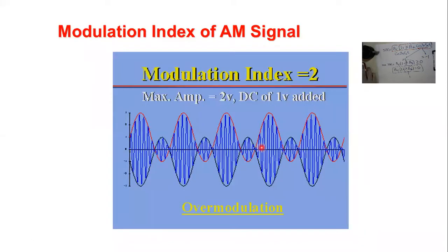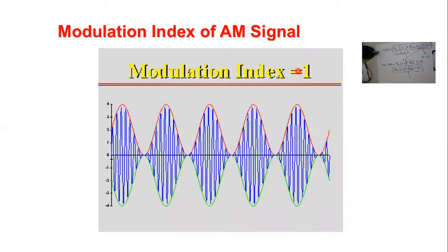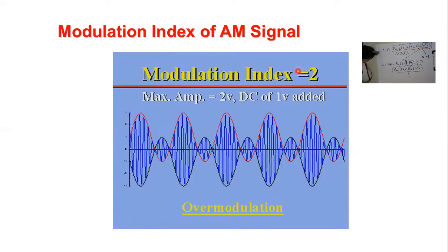And then you have this case, what is called over modulation. If you remember, this is our first case, when we make this phase overlapping. So you can see it here and there. This phase overlapping problem occurs when k, the modulation index, is greater than 1. So these are the three main conditions. Of course, overmodulation is unwanted because it has a discontinuity in the carrier, and also it has a problem with the frequency spectrum.